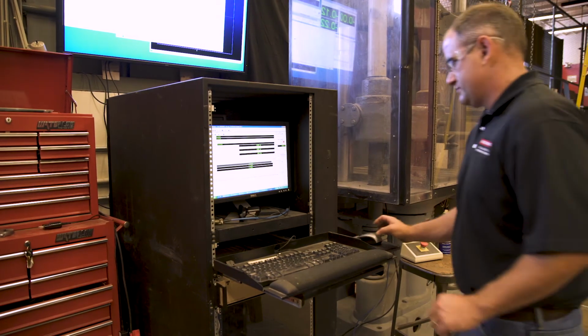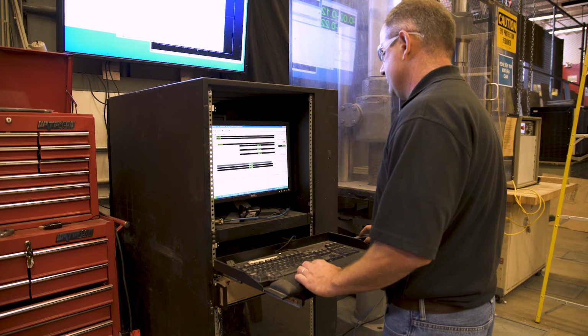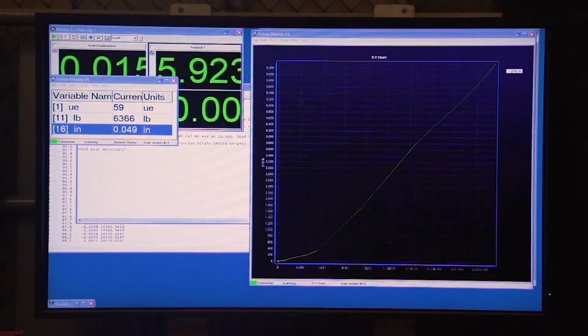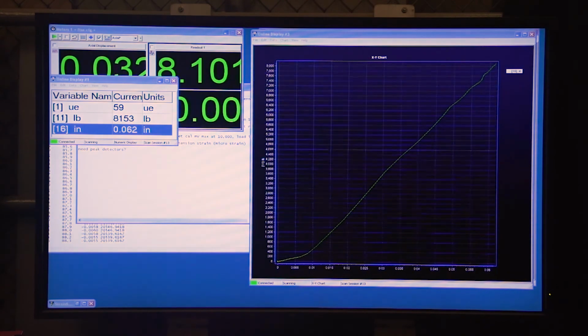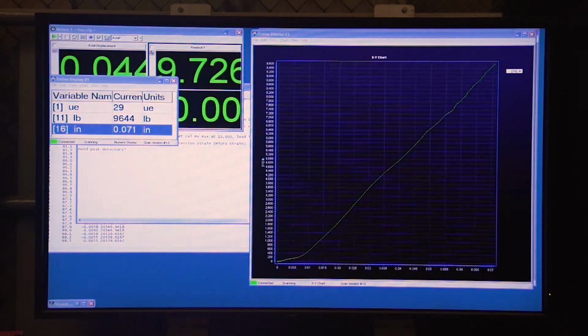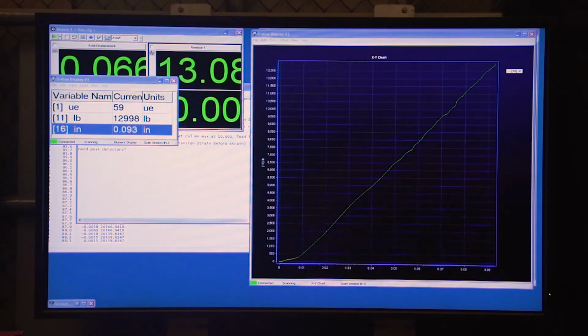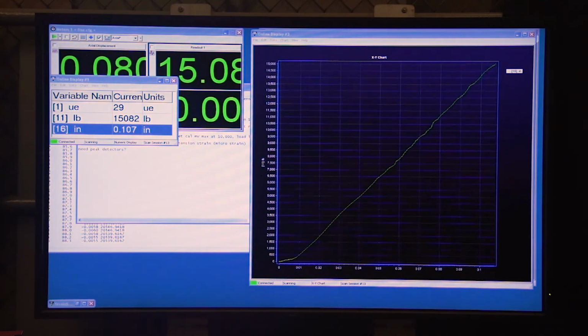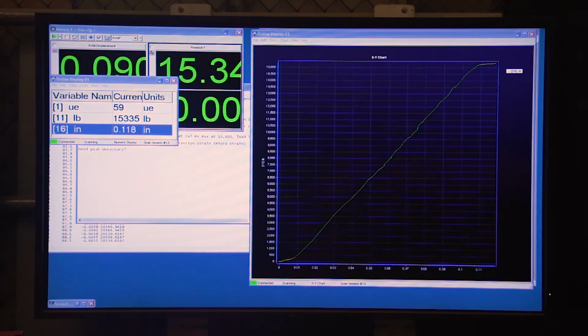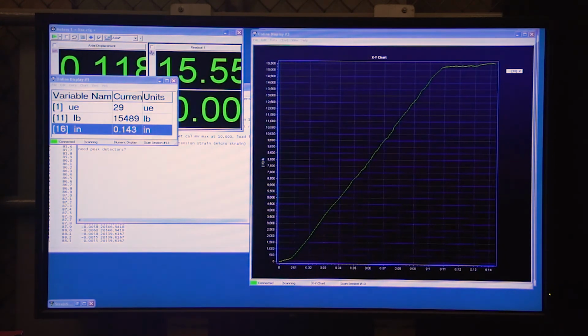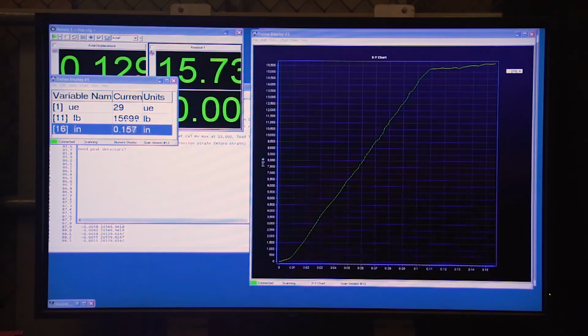The TA will enter the selected displacement rate into the test system software and start the test. Observe the load versus strain curve generated by the test system software. Initially, a linear relationship between load and strain will be observed. However, as the load applied to the specimen continues to increase, the specimen will eventually yield, and a corresponding decay in the slope of the load versus strain curve will be observed.